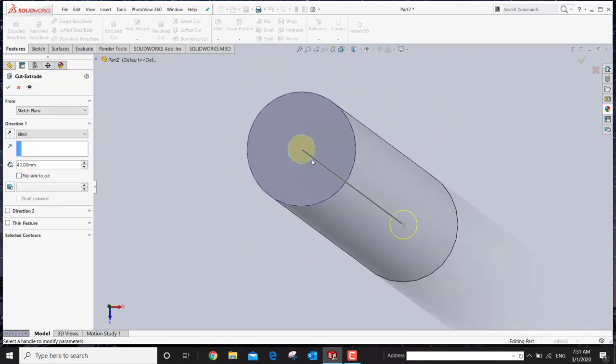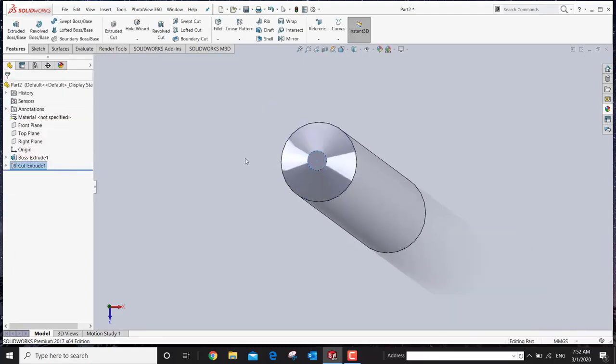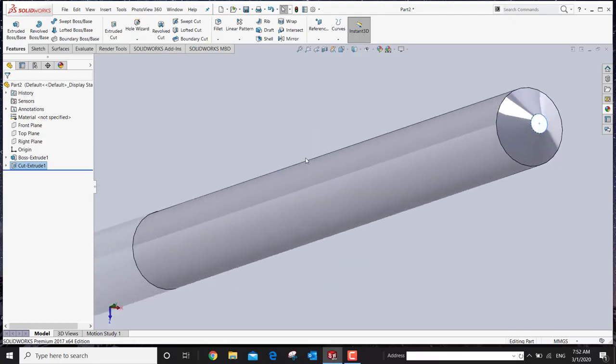This will make a cut along this line, up to this point which is the other side of this object. Change this to 5 millimeters. Tick, flip outside. Use an angle of 55 degrees. This arrow shows that the cut is going in this direction. Click OK. We've made an extruded cut on this three-dimensional object.